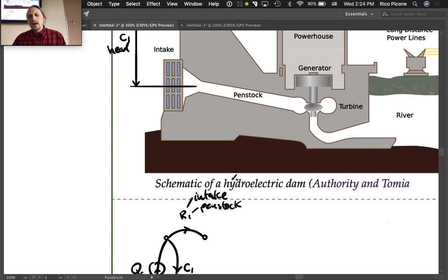So then we've got this penstock. There are other aspects of this penstock. So the first one, if we are thinking of it as being like a pipe, is that there's going to be a lot of fluid moving in one direction, right? Potentially this is a relatively long, relatively thin penstock, and so potentially we have some inertance associated with it, right? Some fluid inductance.